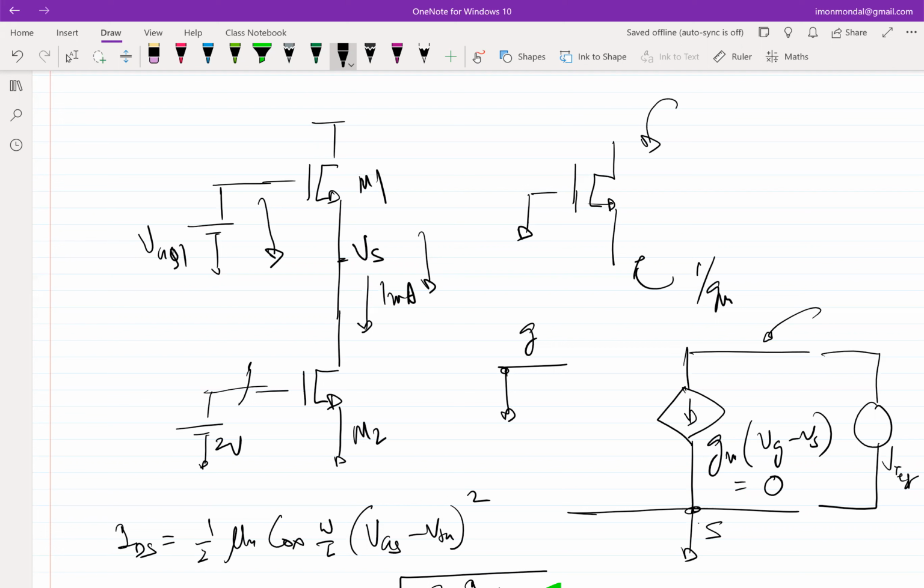So how do you ensure that M2 is always in saturation? In this particular configuration, which is your knob that you have to tweak to ensure that M2 is in saturation? No, I don't want to connect anything to anywhere. This is what it is. Yeah, I can change VGS2. No, I want 1 milliamp, which means I don't want to change this. I don't want to change the sizing of M2. This is whatever we have. VGQ1 is the only handle that I have, right?